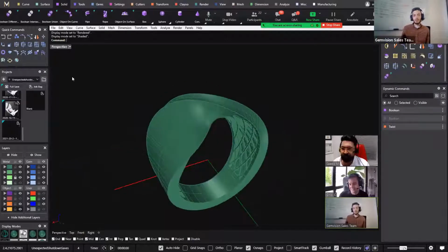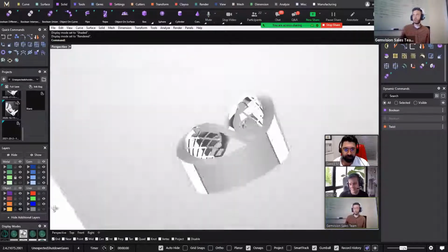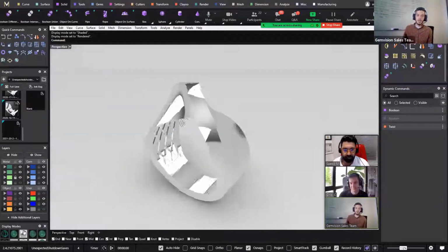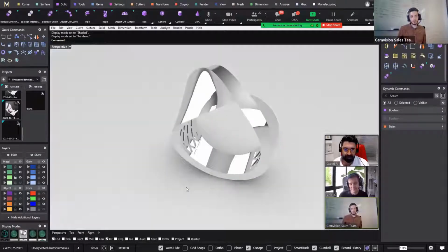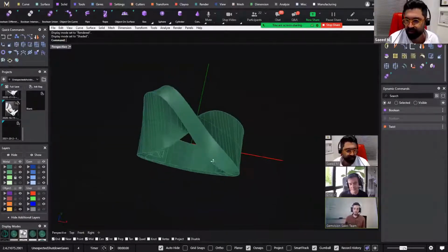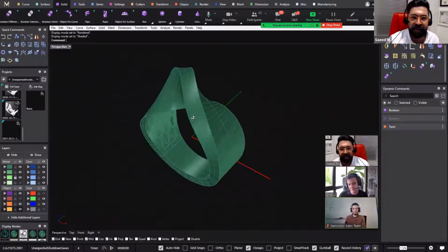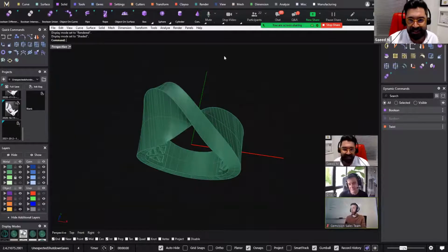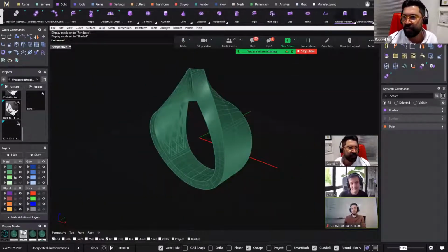As far as the model, I love it. I think a lot of people in MatrixGold get focused on solely using parametric commands, which are absolutely great, but it's also good to know the fundamental commands as well, and some tricks, you know, when you're using the twist command, it gives you a very smooth form. And for having a good render, it's always good to make sharp edges a little bit fillet edge. So the last thing I'm going to do.